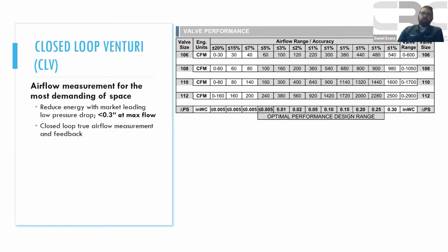It is flow feedback. And what we mean by flow feedback is it's flow feedback by air measurement. So it does measure airflow and then give us what is that true CFM coming back as a measurement, and it's not a derived value or a metered style value coming back. So there's some things we can do with that.